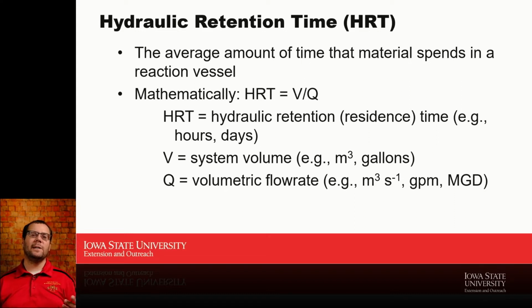So for manure digesters, we're typically in that 25 to 30 day hydraulic retention time. If I'm digesting lignocellulose materials, crop residues, I'll probably be longer than that, somewhere around 40, maybe even up to 60 days, depending on how hard it is to break that material down. On the other hand, if I put an anaerobic digester to help Pepsi or Coke with their sugar water residue that comes out of some of their processes, I might need only a really short hydraulic retention time, somewhere in the neighborhood of 10 to 12 days. And that's the type of place where separating hydraulic and solids retention time really can be a huge advantage.